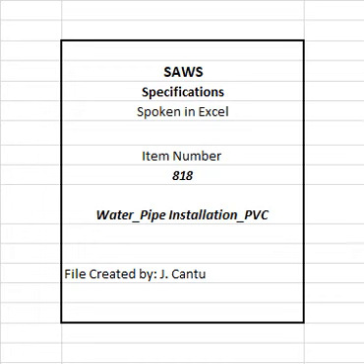E. ASTM D2412, Standard Test Method for Determination of External Loading Characteristics of Plastic Pipe by Parallel Plate Loading. F. ASTM D2444, Standard Test Method for Determination of the Impact Resistance of Thermoplastic Pipe and Fittings by means of a tub, falling weight. G. ASTM D3139, Standard Specification for Joints for Plastic Pressure Pipes using Flexible Elastomeric Seals. H. ASTM F477, Standard Specification for Elastomeric Seals, Gaskets, for joining plastic pipe.